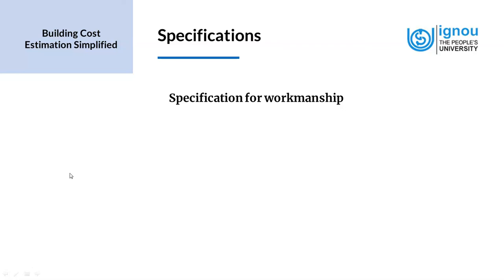If material or skilled labor is not available in the site of the project or even in the vicinity, there is a likelihood that the cost of the construction may go up, and so accordingly such specifications have to be drafted, ensuring that the material that is specified and the skills of workmanship required is actually available.